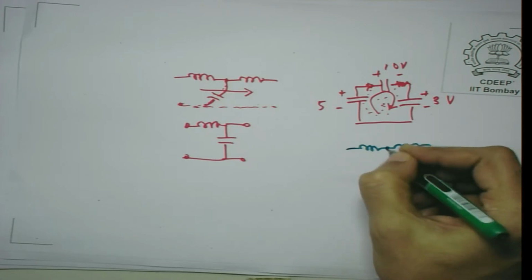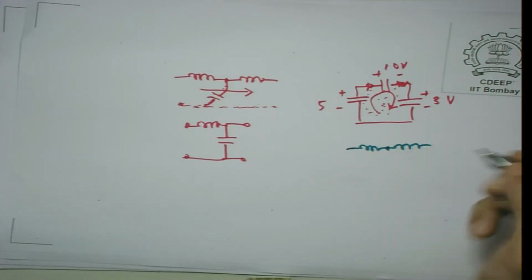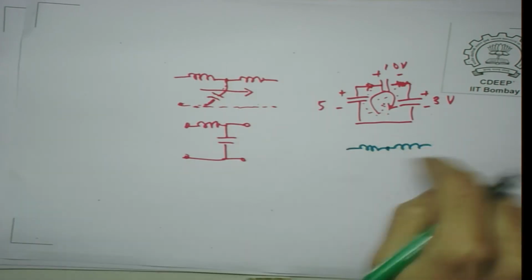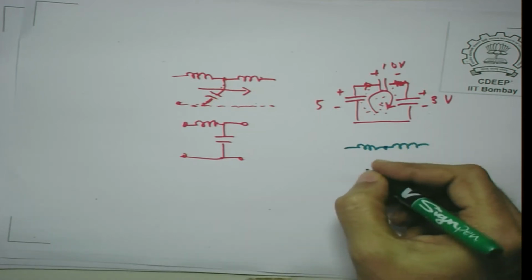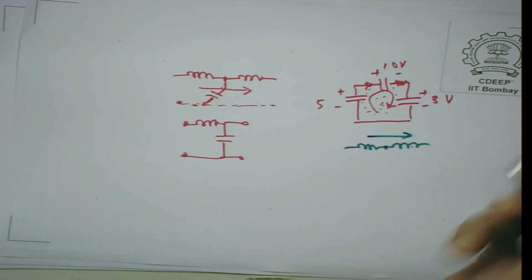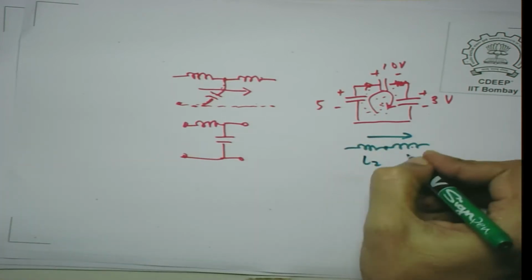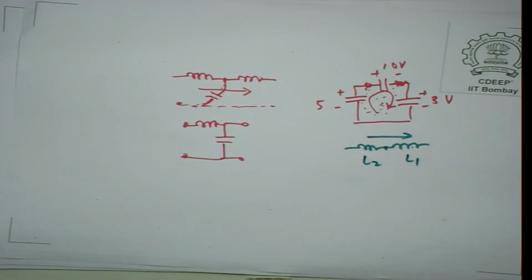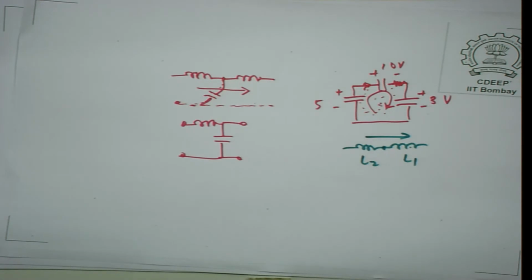You do not require only two initial conditions, one for the inductor and the capacitor. In the unusual case where you have two inductors, you in fact cannot independently specify two ideal inductors with no parasitics between them. You cannot specify the currents independent of each other. So, there is only one state here, even though you may have physically two inductors. If you neglect parasitics here, you have only one state.